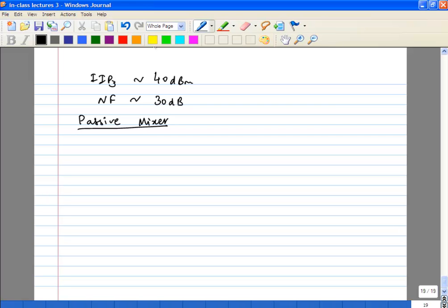No, noise figure is always in dB. Yes, it is a very high value. That is the input noise, it completely drowns out the input noise, that's what it means. So that's why you won't find a lot of people using the potentiometric mixer, except in probably very niche applications where you're interested in linearity. Probably noise is not a big concern.